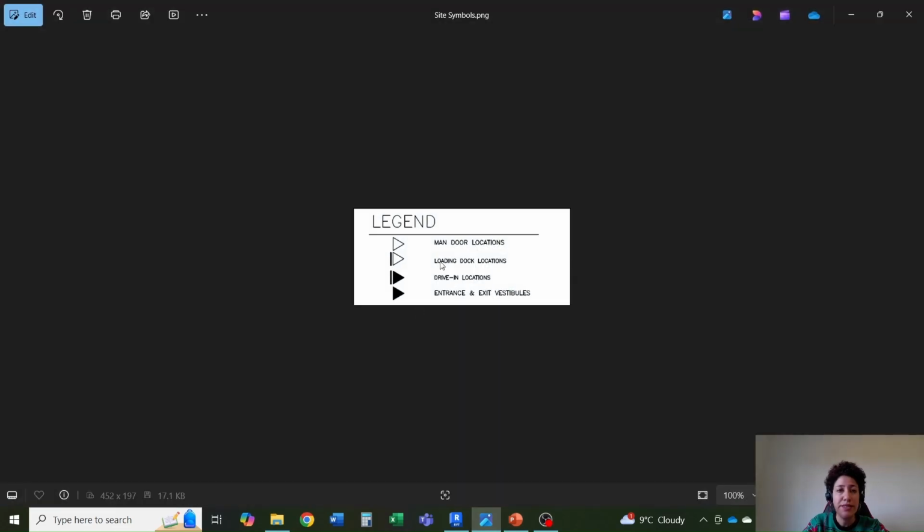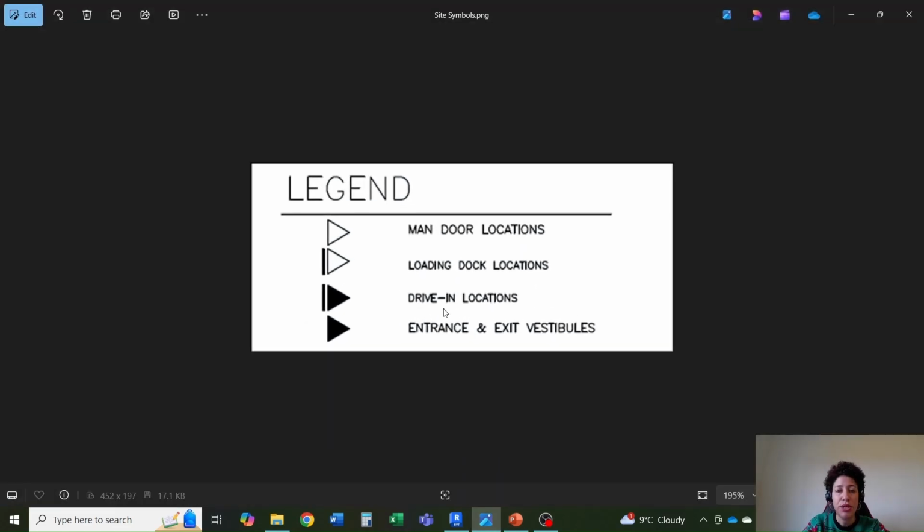As an example, let's say we use these legend items over and over again in our site plans. Instead of creating them in one project, I would suggest that you create them as families so you can use them over and over again. Let's say I'll go with this black one, which also has a field region. First, I'm going to create it as an annotation item. Second, I want to create it as a detail family.